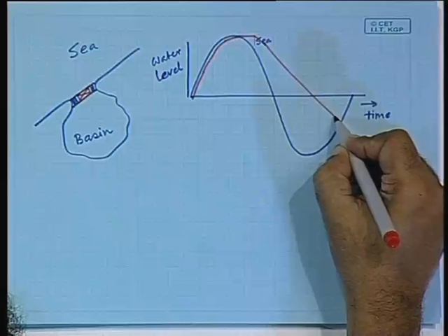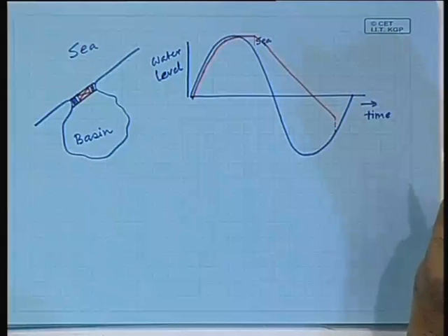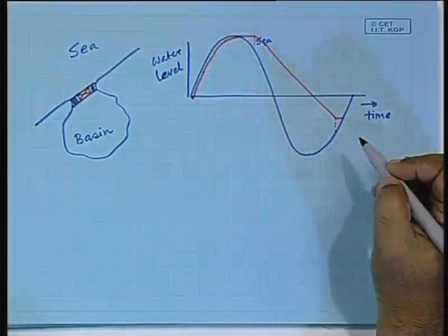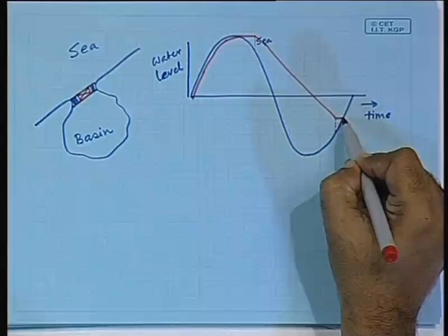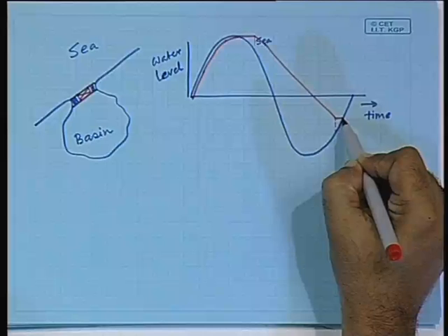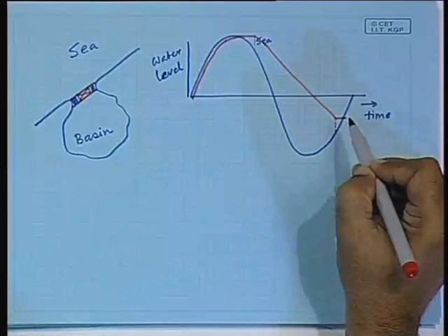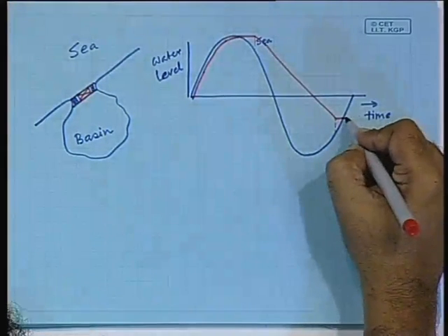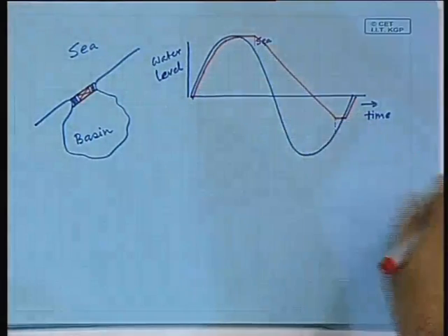And after some time again the head becomes insufficient to generate electricity. Then again the sluice gate is closed. Okay. And then after the two levels become the same, the turbine was closed, the sluice gate is also closed. At this time the sluice gate is open, not the turbine, and then it follows the same route as here. That cycle repeats itself.